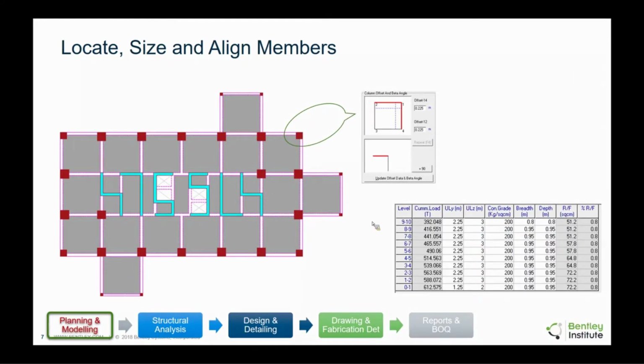We talked about column sizing. You can actually see on the right here, there's a load flow. So it actually works out the complete load flow across levels, and based on that, it suggests the column size. You can suggest to the software that I want the same size over 3 floors, or the next 4 floors. So it actually builds in all that practicality that we tend to do as real engineers in real projects. It also does a lot of parameterization.